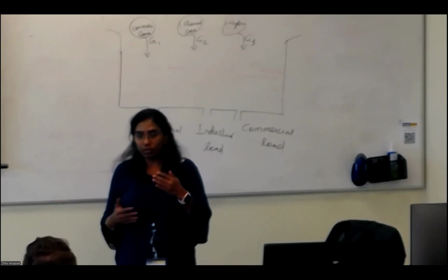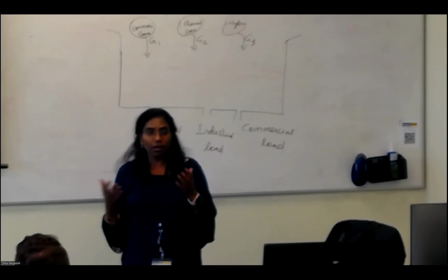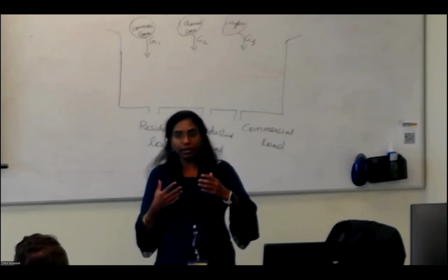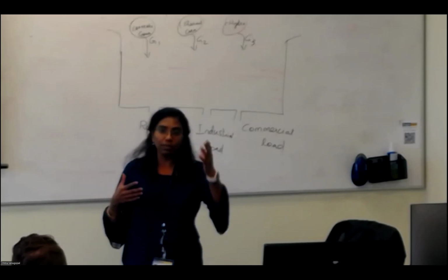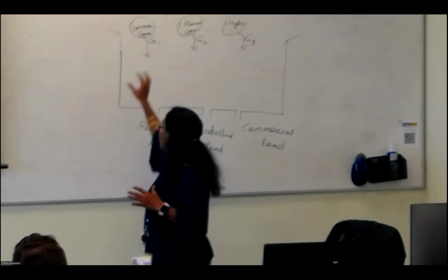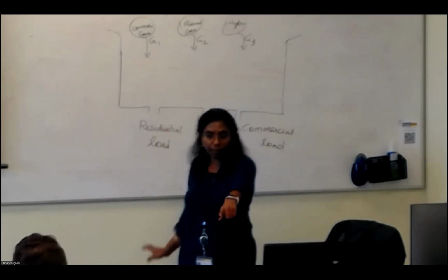Okay, so when you have to run all the generators in parallel, for the costliest generators, like oil and gas generators, we take less power, and for the less costly ones, we can take more power. So how much participation factor each generator has in this grid to supply these loads, that is what we call the participation factor.